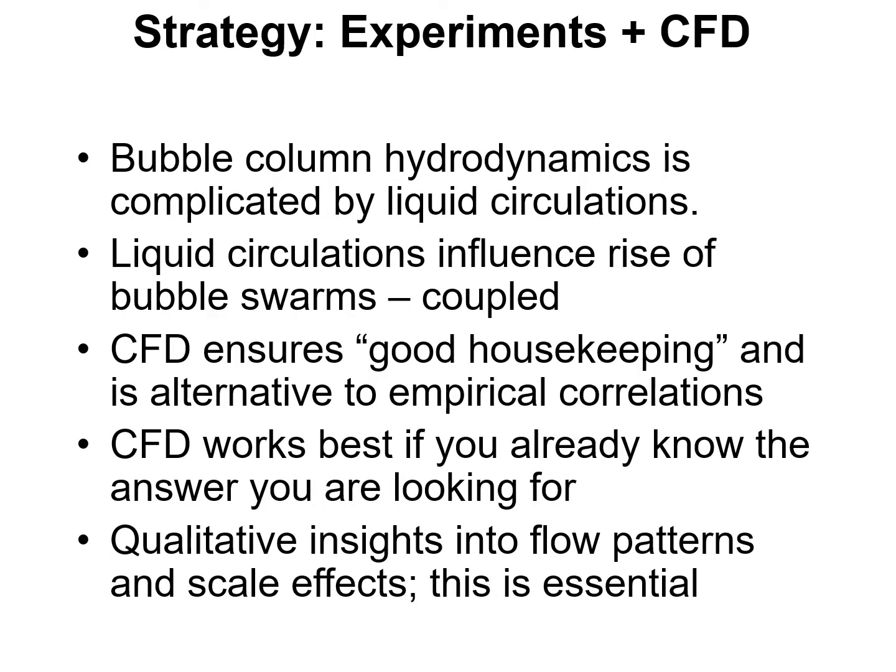I list here some of the key points of the scale-up strategy I'm proposing based on experiments in cold flow units coupled with CFD simulations. The important points to note are that the bubble column hydrodynamics is complicated by liquid circulations. The liquid circulations influence the rise of bubble swarms, and these are coupled because the circulations are induced by bubble swarms, and the rise velocity of the bubble swarms is influenced by the liquid circulations.